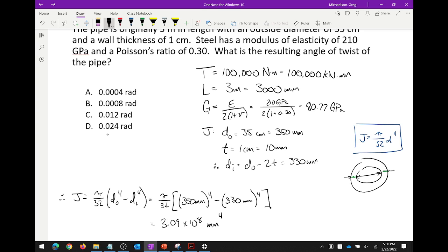Let me give you another example of where engineers have resolved this in another light. The moment of inertia of a beam is also listed in inches to the 4th, but there is an incredibly convenient way of expressing that, and that's through a radius of gyration. So what do we do with the radius of gyration? We take a moment of inertia, we divide it by the area, and we take the square root. You know those L over R values that we looked up in steel design? What do you think R is? R is just the moment of inertia divided by the area, take the square root. So R is basically the same as I, it's just normalized a little bit.